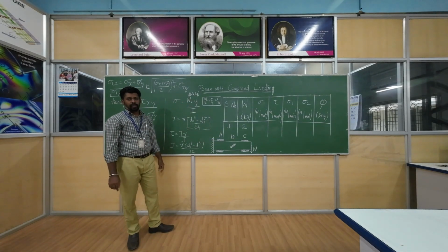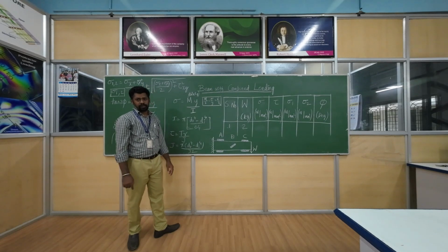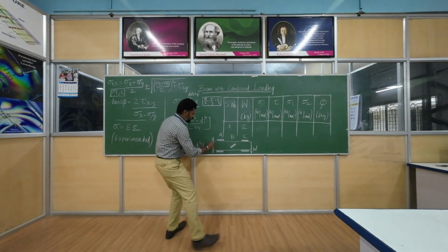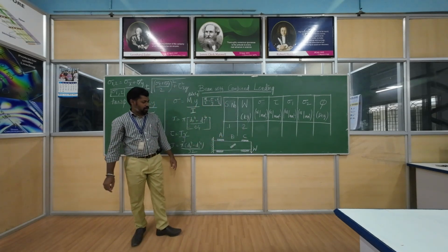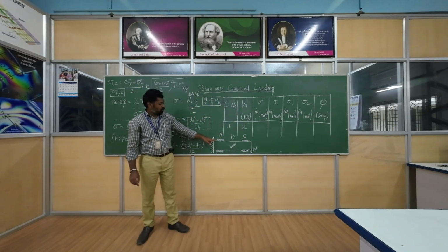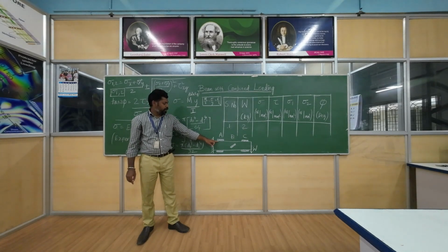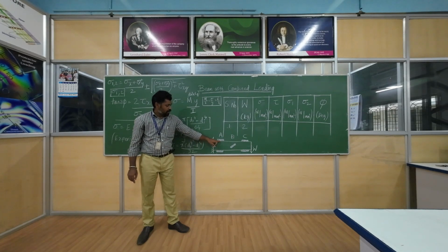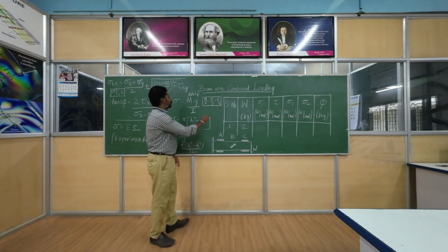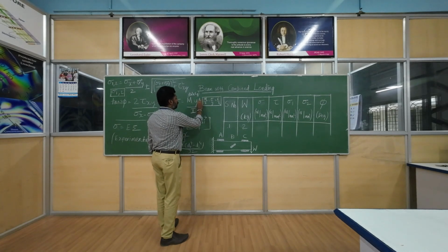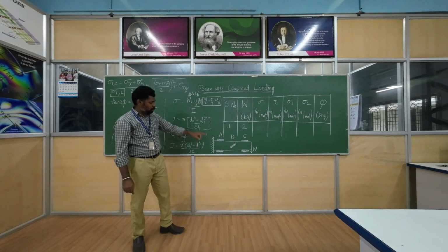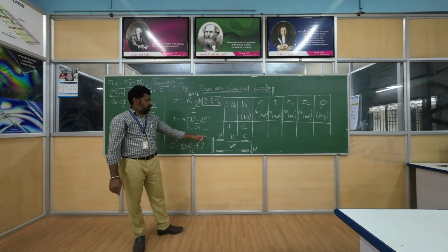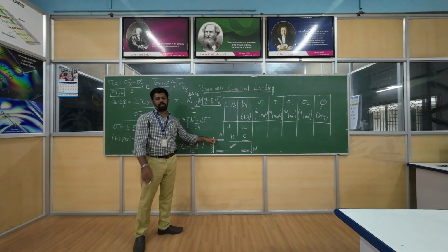Now what is y? I told you this is from the neutral axis. So we all know that for a circular cross section, the neutral axis would be at the middle of that beam. We know that the maximum stress would be occurring at the top or bottom of the beam. So I can write my y as D by 2. So D is diameter, D naught by 2 would be the y. At D naught by 2, the beam will experience the maximum stress.